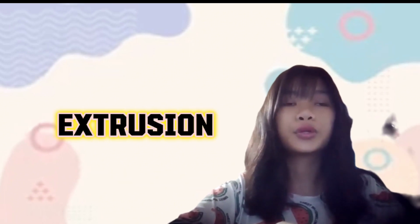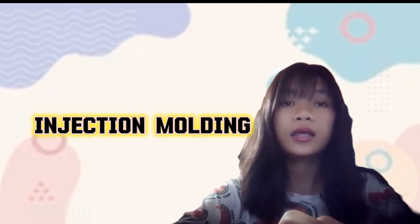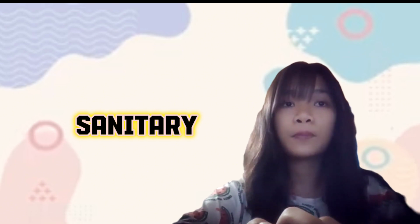Next is extrusion. This means pushing a material through a die to create objects with a consistent cross-sectional profile, like pipes and tubing. The next is injection molding. Common in plastics manufacturing, where molten plastic is injected into a mold to form various products. Then we have sintering, often used in powder metallurgy to compact and form objects by heating without melting.